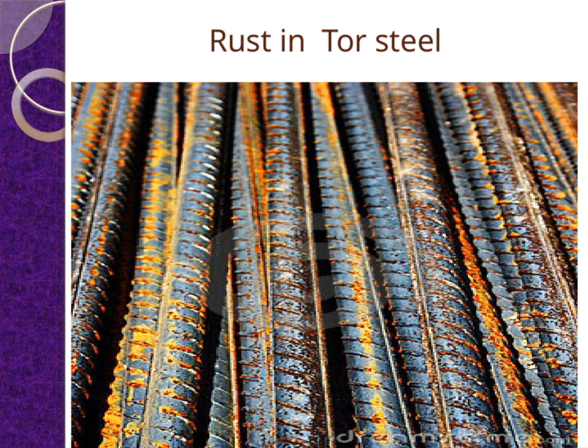For example, excessive rust can lead to delamination or failure of the reinforcement, elevating the risk of structural collapse. That's why during design and maintenance, we need to consider protective measures like coatings, corrosion inhibitors, or even using more corrosion-resistant materials. So, in the context of overall structural durability, managing rust in Tor steel is a key aspect that ensures long-term performance and safety of our constructions.